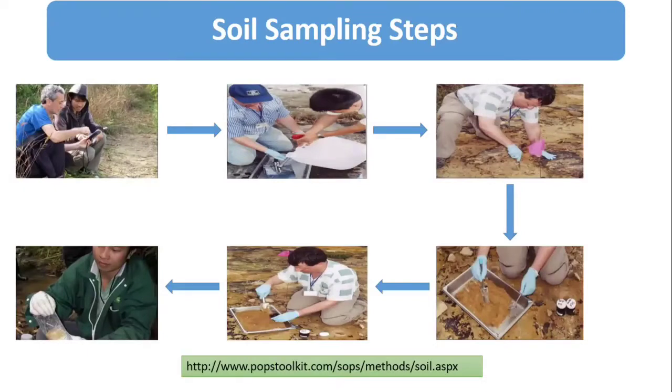Ensure that there are waterproof labels on the containers, including the sampling site number, date of sampling, type of sample, and the name of the project. Here we used to make some errors, like we will take some markers to mark our sampling bottles. Suppose we will mark A2, something like that. But the problem is that we don't know whether during the sampling day we will have some rain or there will be a chance of water spilling onto your bottle.